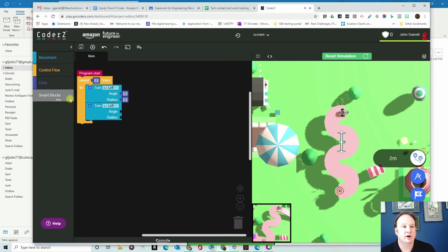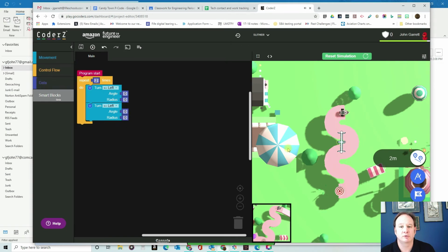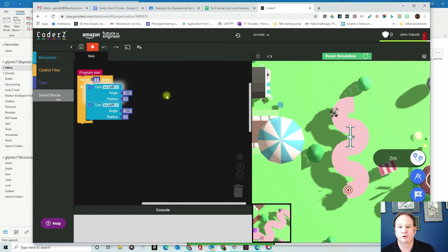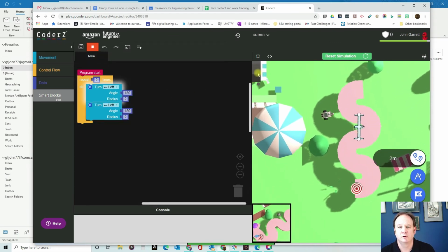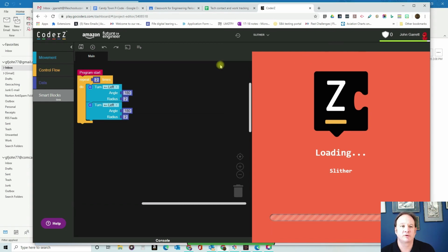Now, I'm doing this incorrectly to illustrate a point, because I know some of you are probably going to do this. You hurry through things and you're going, okay, great, got my radius. Okay, so 180, 180, and 2, and 2. And all right, perfect, run it. And here we go. So I'm turning, and wait a minute. There goes my robot. Stop, stop, stop. So those of you who weren't figured out, I'm going to reset the simulation here.